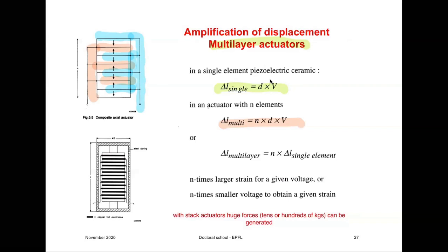While in the direction of polarization, you can usually apply large forces, and the compression is needed, among other things, because piezoelectric materials, ceramic materials that are mostly used for piezoelectric actuators, can be easily broken on tension. But on compression they are much more difficult to break, and that is because under compression you close the cracks and they cannot propagate that easily.